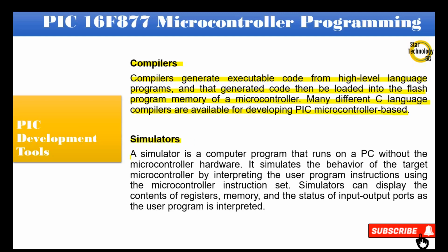Simulators. A simulator is a computer program that runs on a PC without the microcontroller hardware. It simulates the behavior of the target microcontroller by interpreting the user program instructions using the microcontroller instruction set. Simulators can display the contents of registers, memory, and the status of input-output ports as the user program is interpreted.